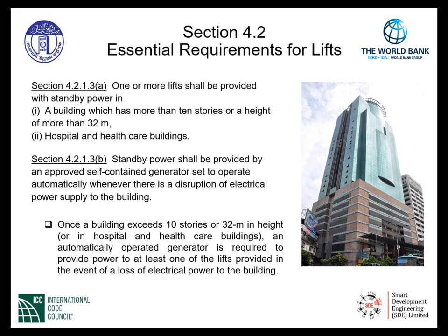Section 4.2.1.3, item A. One or more lifts shall be provided with standby power in a building that has more than 10 stories or a height of more than 32 meters. Hospital and healthcare buildings are also required to provide standby power. This is essential due to the fact that the story or height of the building is now getting quite high, and hospital and healthcare buildings need this essential power to be provided in these particular buildings.